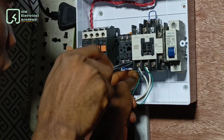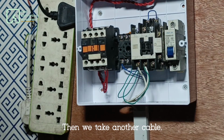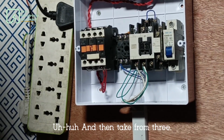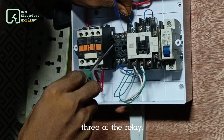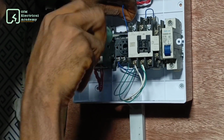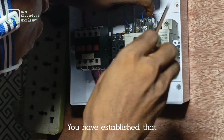Okay, remember we are still working on contactor 1. That's where we are still working. Then we take another small cable, and take from 3 of the relay to the A1 coil terminal of our contactor 1. Okay, you have established that.